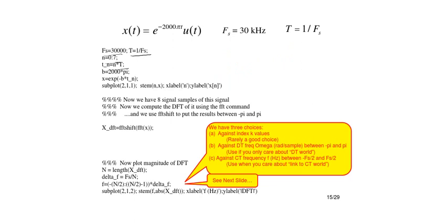Now we compute the FFT of x, and then we shift it so that you get the positive half of the spectrum, and then we can plot it for every frequency point. So this command basically provides you the frequency spacing. I'll explain this like this. Let's say that you draw the spectrum. So these are frequency points, right? For some frequency point you get a particular frequency, right?